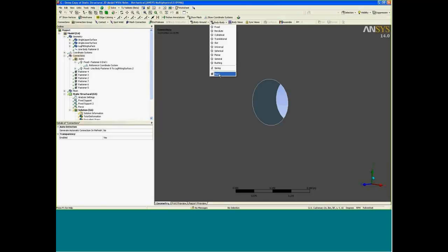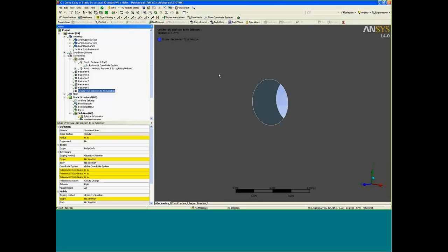Essentially, this will automatically create a beam 180 for us and connect the ends to where we specify. So let me insert a beam. This beam, by default, has a circular cross-section. So this is one where it must be circular, whereas utilizing the line bodies and actual beam cross-sections, you can create whichever you like. In this case, let's create a titanium alloy fastener, then put in our radius here, 0.0945 for our Hi-Lok diameter, and here's our body-to-body.